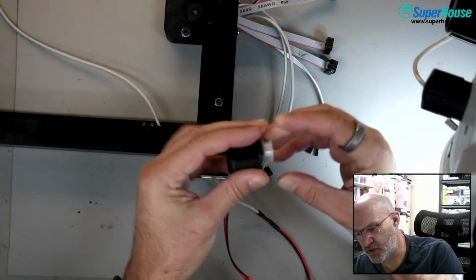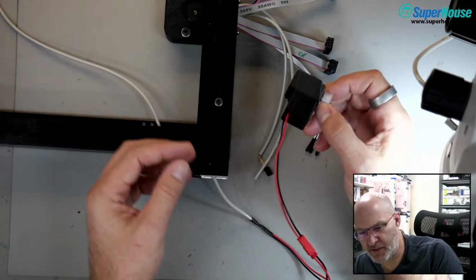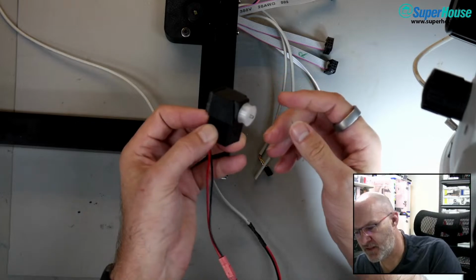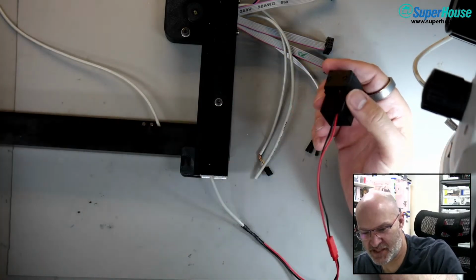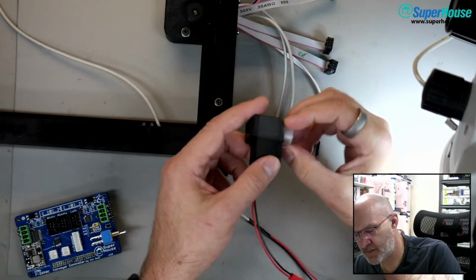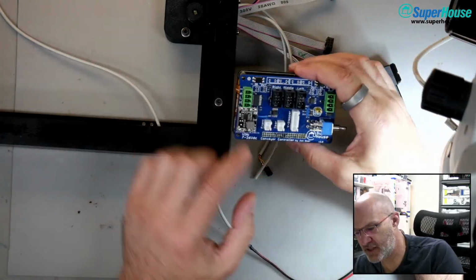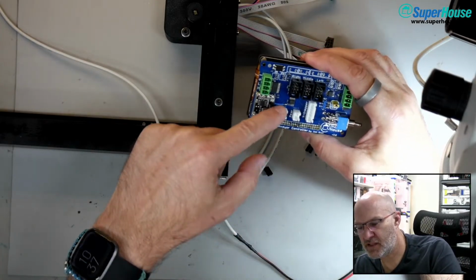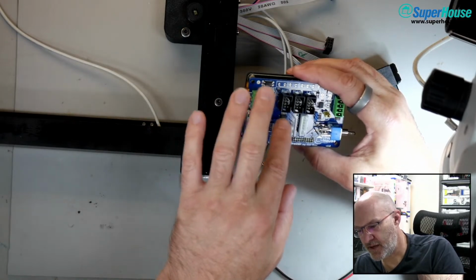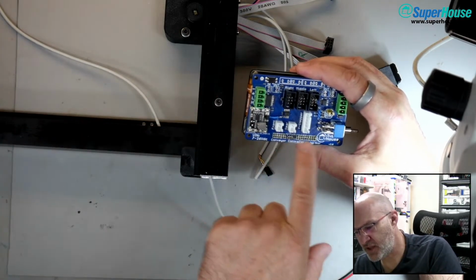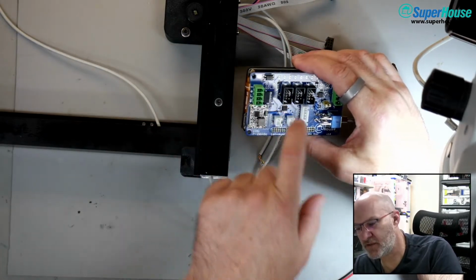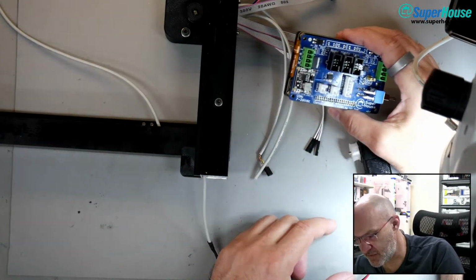You can get them in different voltages. For whatever reason, my first version I was using 5 volt rated motors, and then I switched to 12 volt rated motors. I don't even remember why. It might have been some performance related thing. Something to do with getting the ratio correct. Oh, actually, I think it also may have been to do with power isolation, because the power that feeds into that little H bridge, which runs these motors, I wanted to have isolated on the input side of the voltage regulator that goes to everything else on the board, including the ESP32. I didn't want the motors running off the same 5 volt rail that feeds everything else.